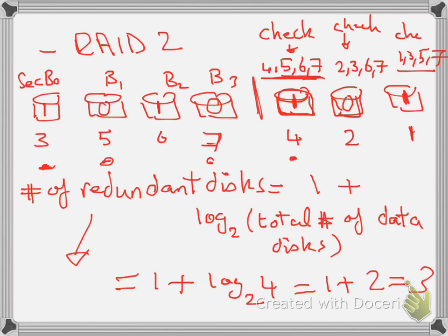And by default, with this, we will calculate the even parity. But if I'm asking you to calculate odd parity, you will do the same, but you should ensure that the number of ones is odd. If it is even parity, the number of ones should be even.